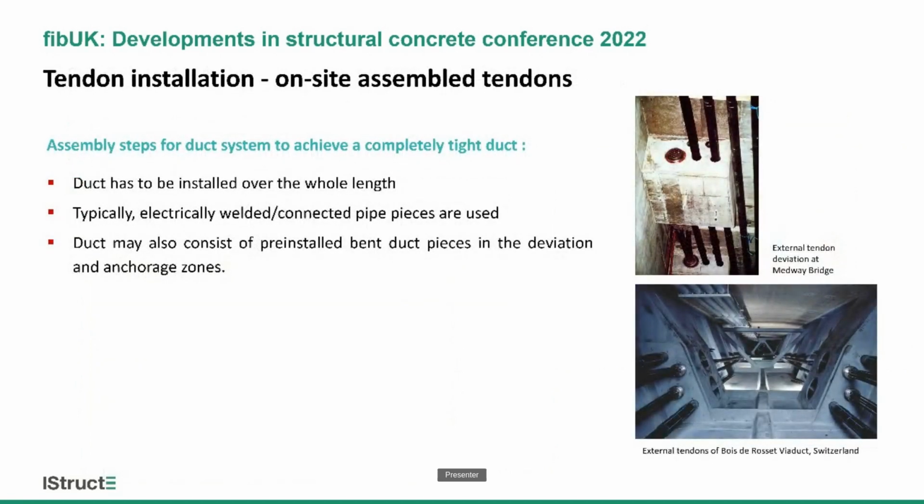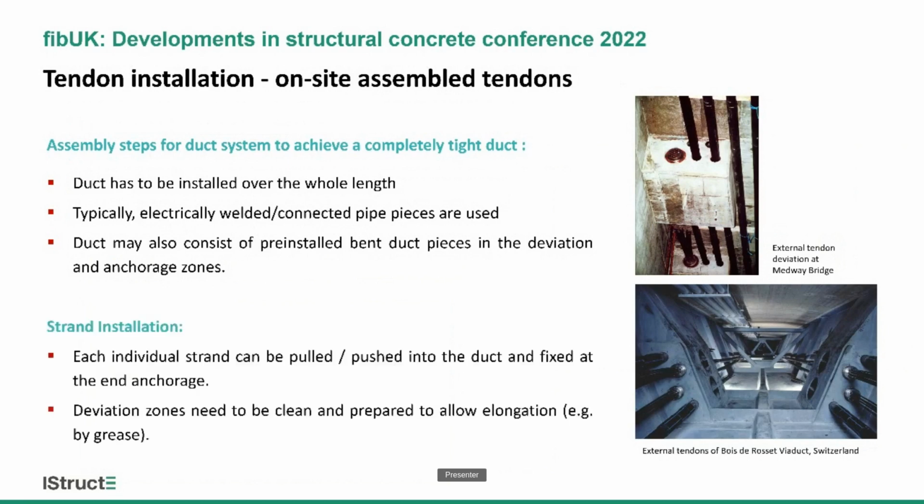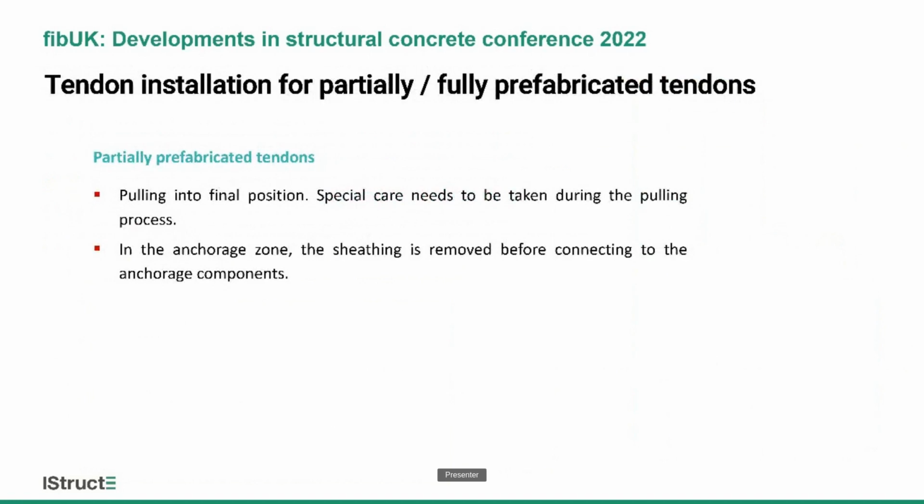Coming to the installation for on-site assembled tendons, typically you start with installing the duct. Special consideration is taken where you have valves for injection, also considering where you have deviators and so on, when typically the strand is installed one by one. Come to the further works in a minute.